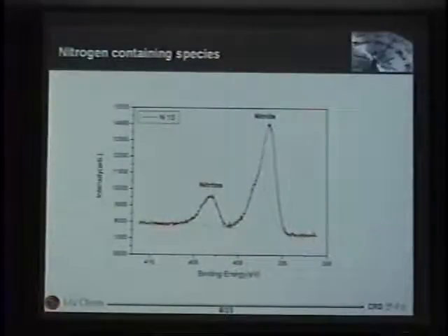So what people insist is that when they treat the ITO surface with oxygen plasma, the concentration, the stoichiometry of indium, tin, and oxygen is the same at the surface region of the ITO and the bulk region of the ITO. So when you apply the voltage, you can minimize the drift of the metals caused by the different stoichiometry. But instead of balancing the bulk and surface stoichiometry, we create a different surface composition.